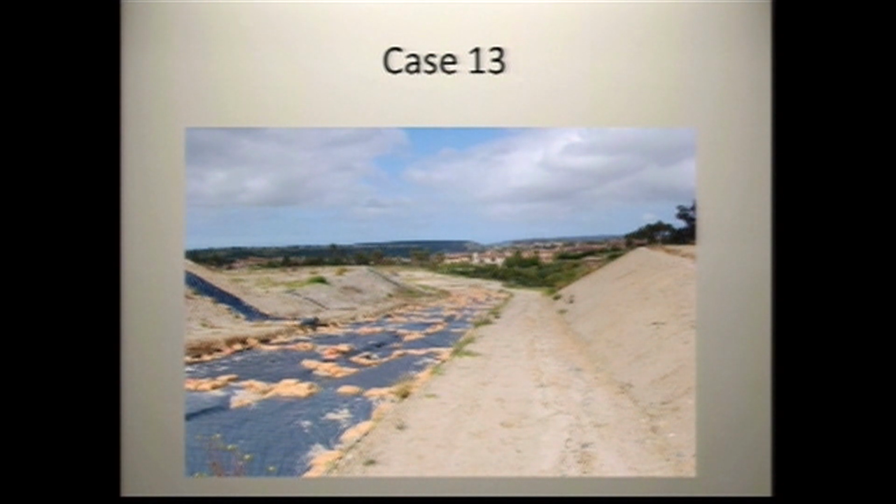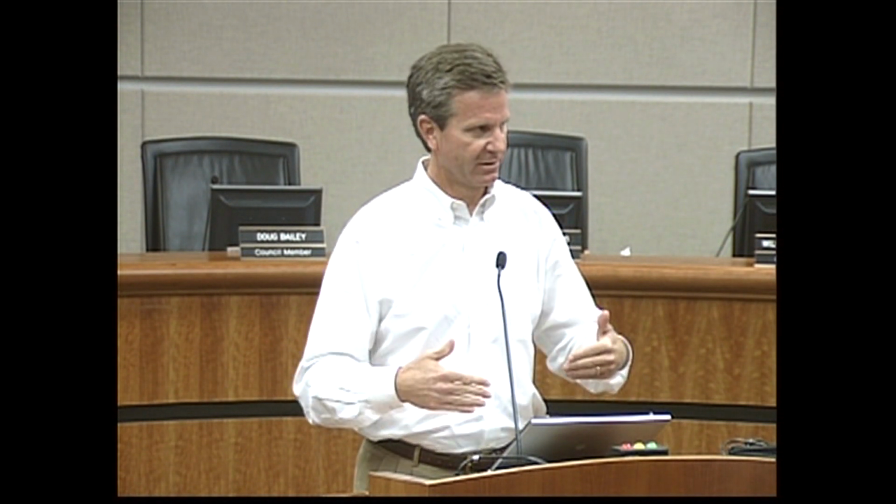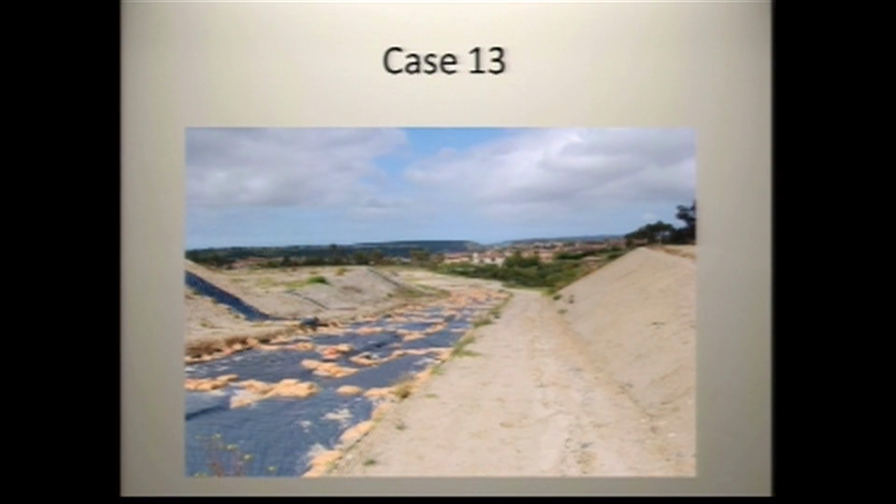In this case, what we did was pave the street. We just put down 2 inches of AC, which was going to be sacrificial for later, because this is an 8% street, and this is kind of sandy material, so there's not a lot else you could do. If you had enough gravel bags to stop it, you'd have 700 per foot or something like that. The other problem was, too, you can see the parkway area wasn't protected, and there's a little line of a rill starting going down there, too.